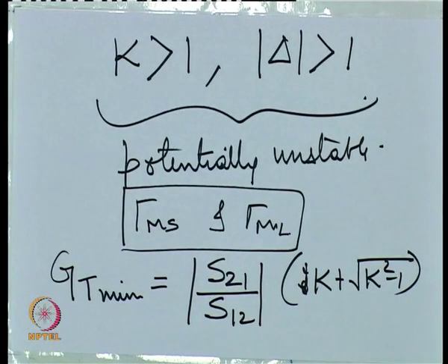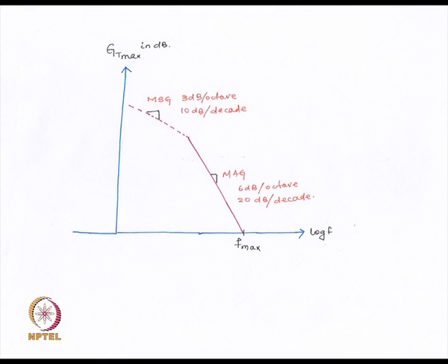And if we go to the slides on the monitor for a moment, this is the typical GT versus frequency curve for a standard RF device. We see that for high frequencies, it is unconditionally stable, and that's why this MAG exists. But for lower frequencies, this MSG is the specification at the stability boundary that is given. This is often a graph that is supplied with RF devices, and we see that at lower frequencies, the device